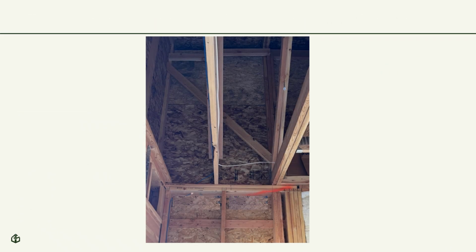This heel exceeds 4 feet, and the panel section is not blocked at the top or bottom or at its horizontal joint. In order to assure that the loads are properly transferred to the brace wall panel below, engineering is required. It is possible that the engineering for this purpose can be included as part of the engineering for the entire truss system.